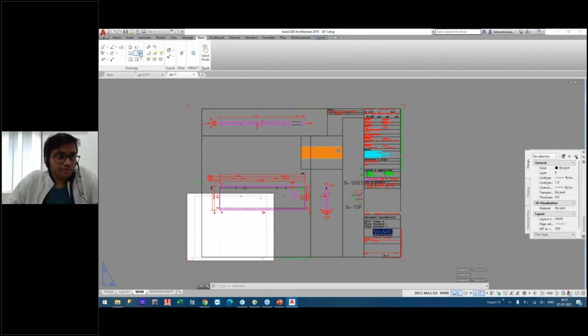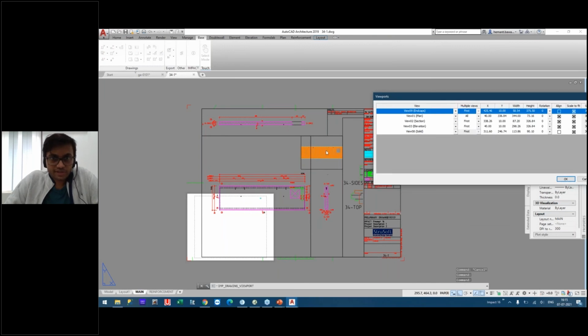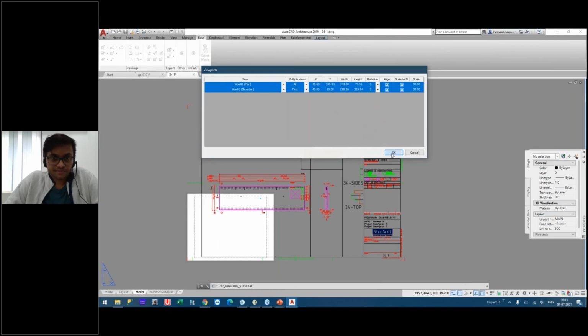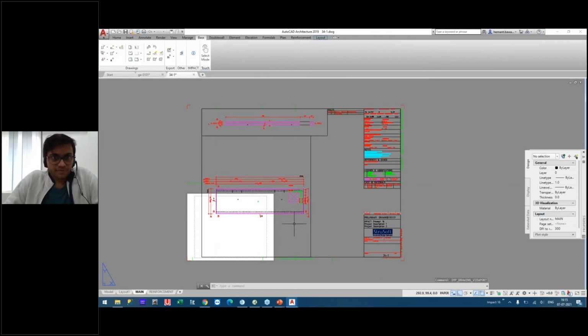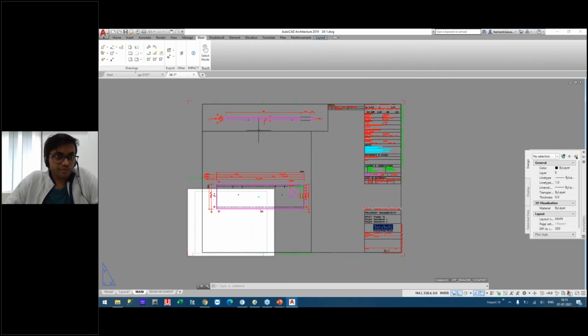I will go into our viewports. I will delete these three of those because I need to adjust the section, this solid portion, and also the end cap view. So I will be clearing those three: end caps, section, and then the solid view. Just delete this and click OK. Okay, now we only have the main elevation and the top plan view.